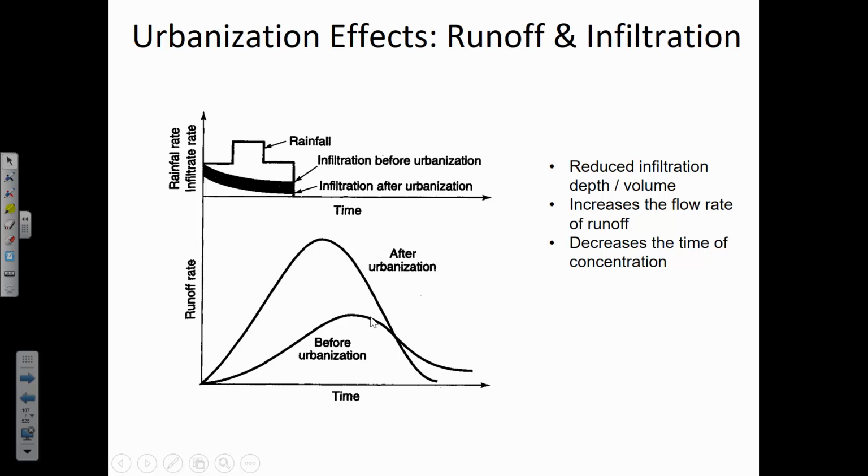Okay, so why? Let's explain the why of both of those. Why does urbanization, taking raw land and turning it into buildings and roads and homes and pavement, give you a higher peak runoff? Exactly, right. So there's not as much water being absorbed by the ground, and so then it has to go to runoff because inevitably the development is going to make the surface more impervious.